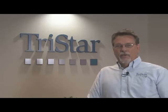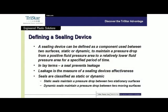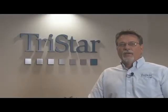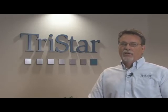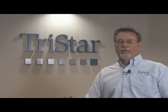Let's first take a look at the definition of a seal, and this is going to be the Mr. Science definition. A sealing device can be defined as a component used between two surfaces, static or dynamic, to maintain a pressure drop from a positive fluid pressure area to a relatively lower fluid pressure area for a specified period of time. That is the Mr. Science definition. My definition as a layman is a seal prevents leakage. That's it, bottom line. And it's the effectiveness of that seal, through its design and through the material, that makes it a good pressure reducer or a bad pressure reducer. So we're going to talk a little bit about what makes a good seal.